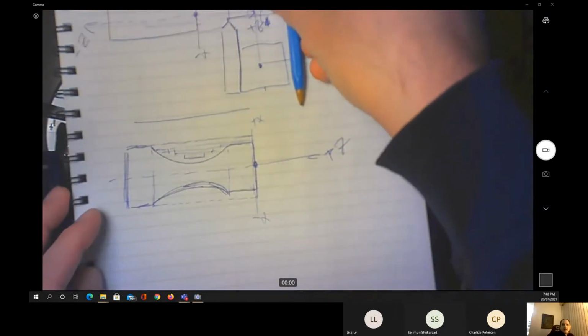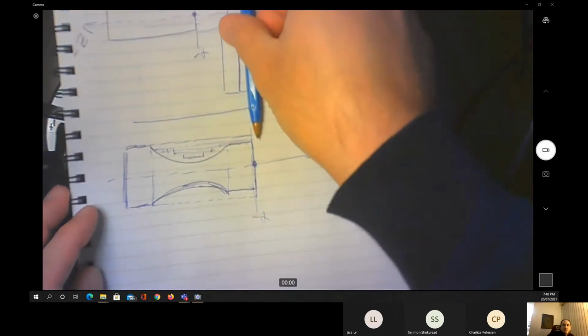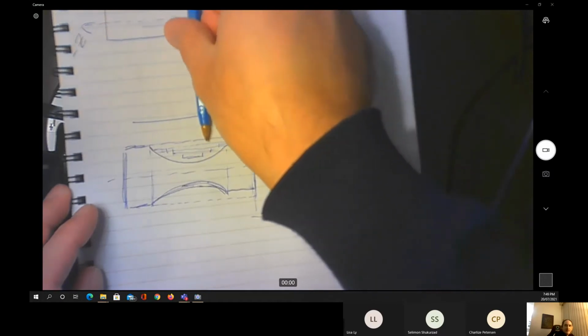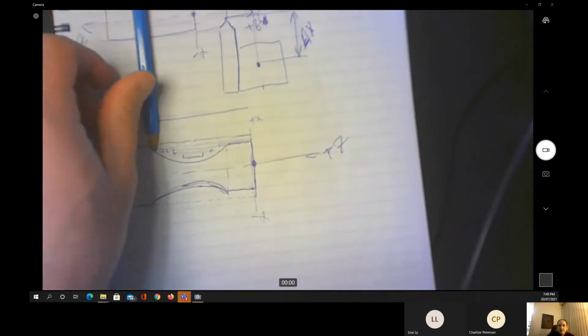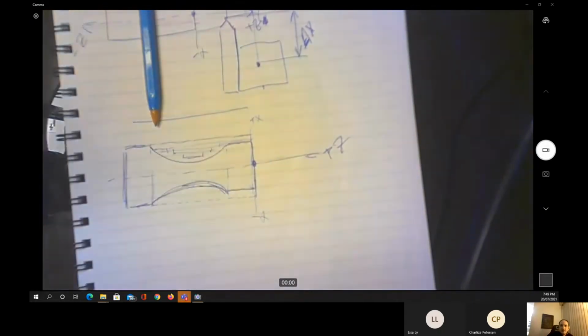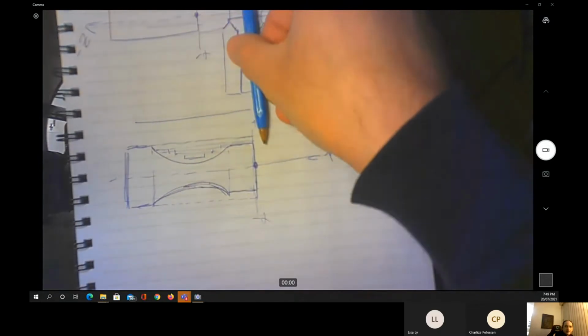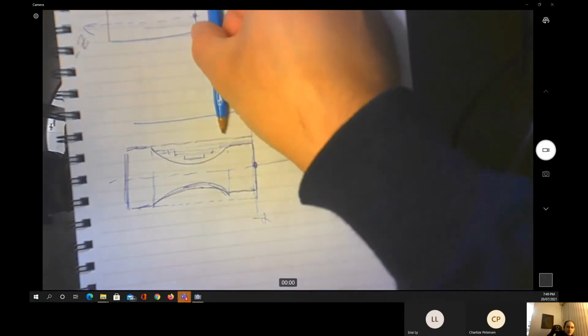The cutting tool will be here. It will travel to here. We set the depth of the cut. Then it's going to move all the way down to perform the cut. When it reaches this step, it's going to leave the part, travel all the way back, then go deeper and do the same movement. Stop here. Going to leave the part. We're going to this position.